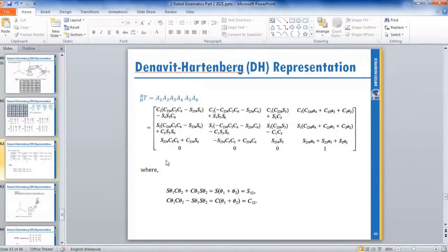So this matrix formula will be specific for your robot design. If you design a new robot, and you want the robot to know the position and the orientation of the gripper, we use the DH method. After you multiply with the length of your robot arm and the joint angle, you will get a specific matrix for your robot.